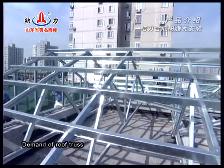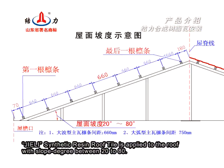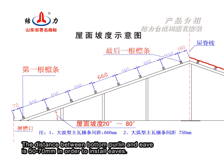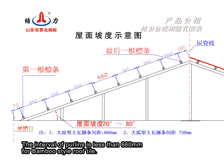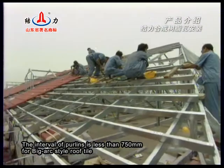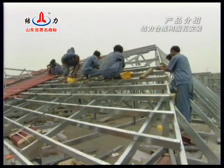Demand of roof truss. Geely synthetic resin roof tile is applied to the roof with slope degree between 20 to 80. The distance between top purlin and ridge line is 180 mm in order to install top ridge tile easily. The distance between bottom purlin and eave is 50 to 70 mm in order to install eaves. The interval of purlins is less than 660 mm for bamboo style roof tile. The interval of purlins is less than 750 mm for big arc style roof tile.